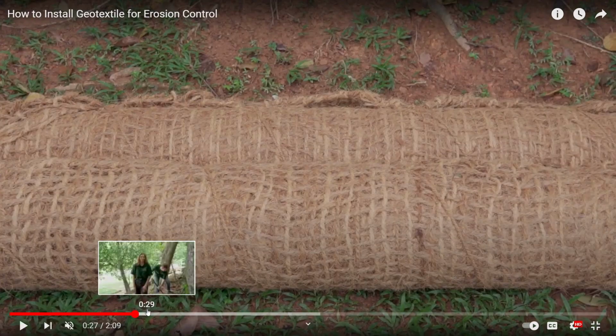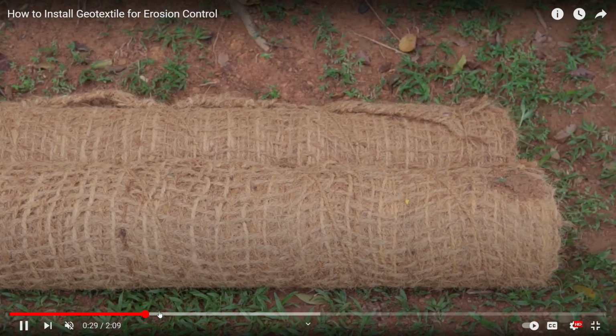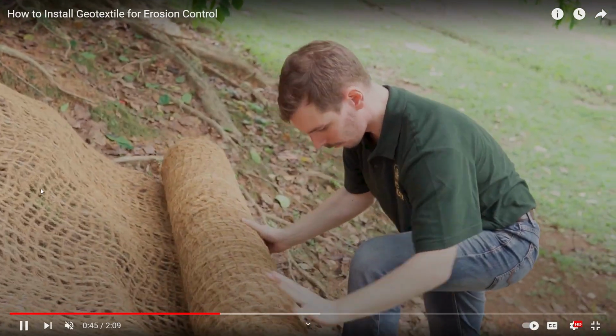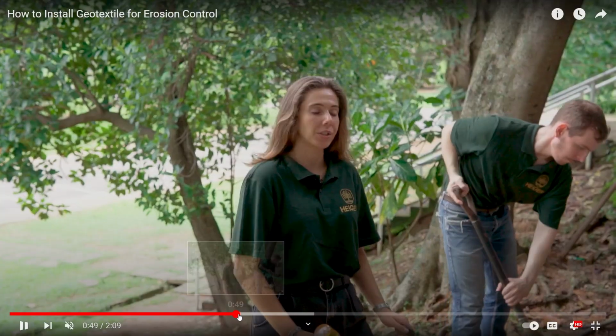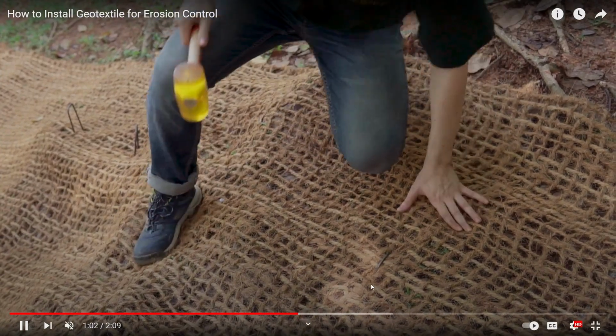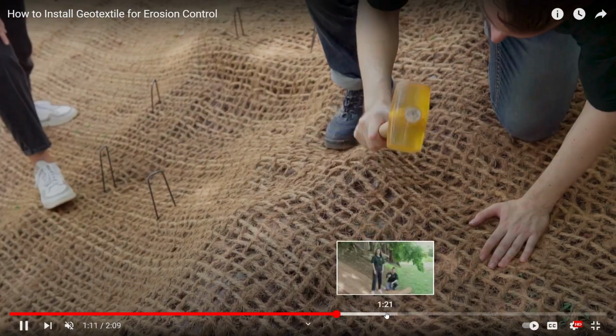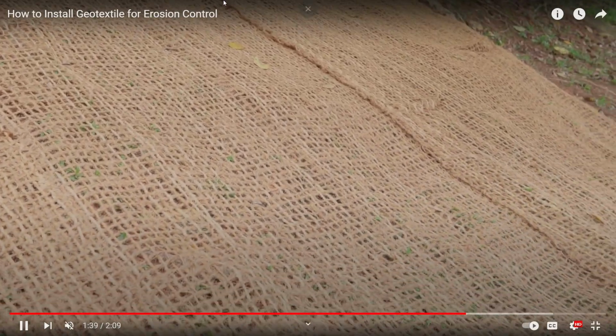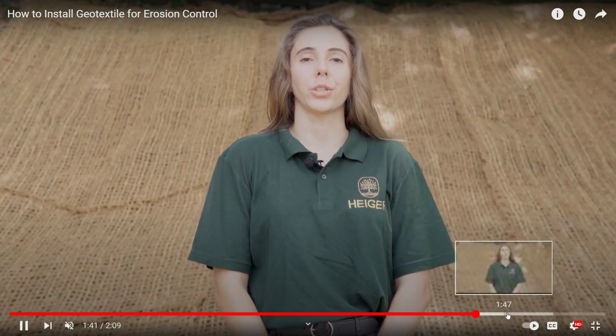and see how it is fixed. We have these steel pegs, and using these pegs you can easily fix it. These are the rolls. It is fixed at one end and just rolled down, and at equal intervals it is pegged into the soil. You can see how beautifully this geotextile has been laid.